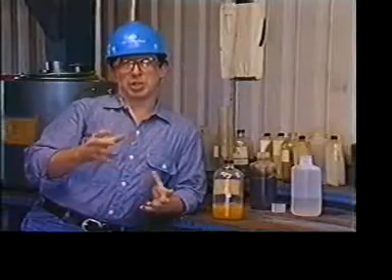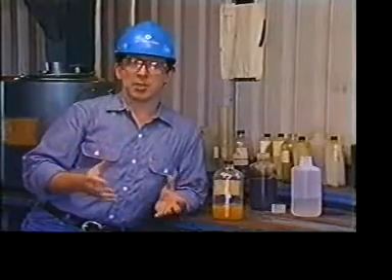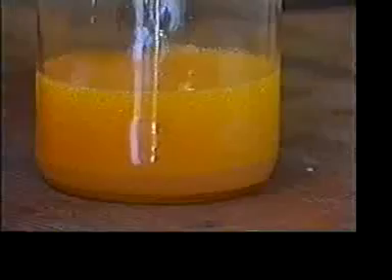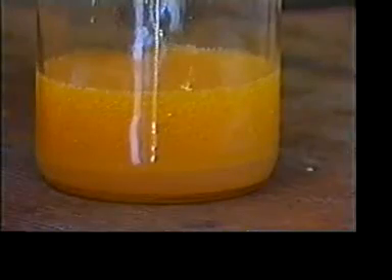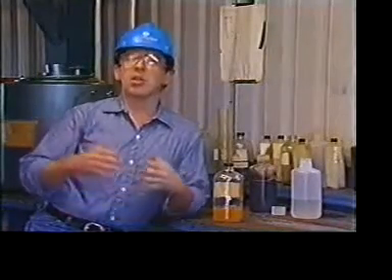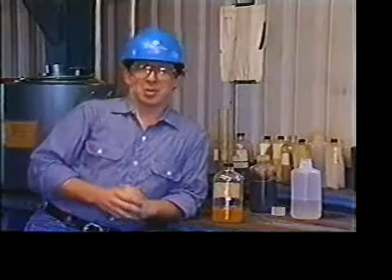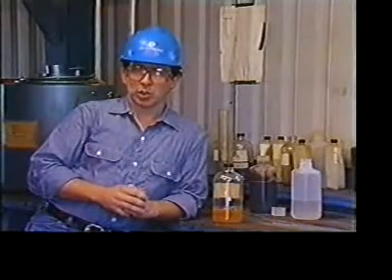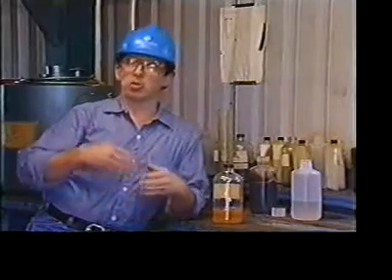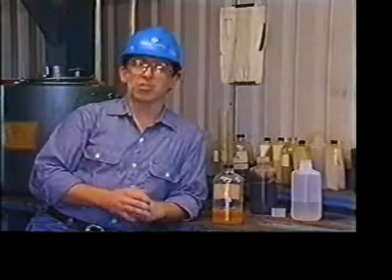We have our emulsion. The simplest way to treat an emulsion is through settling. Since water is heavier than oil, it will settle to the bottom of a vessel, just as our emulsion is doing here. Now, the time needed to completely separate an emulsion is called settling time. Though some emulsions can be adequately treated with settling, it can be a slow process. So one way to speed up this process is to add heat.